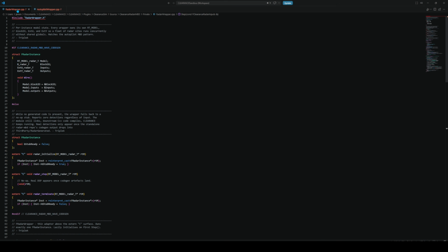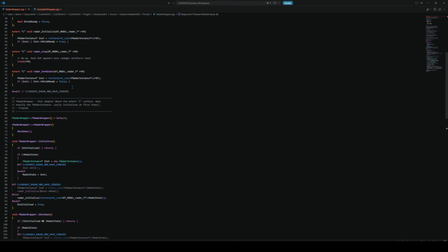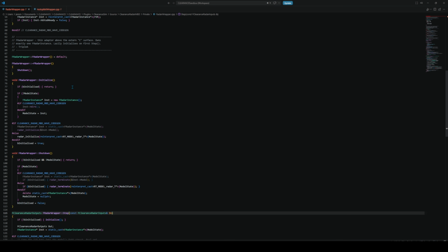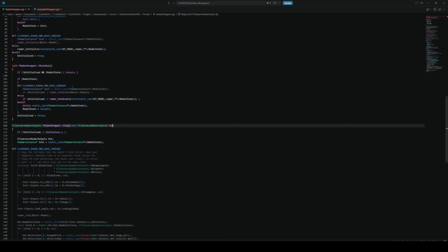And the radar wrapper is sort of the same pattern. You feed it a cube of IQ samples, you call the radar step, and you get the detections back. I build that cube on the clearance side, one contribution per aircraft with its range, bearing, and Doppler baked in. Everything after that is just generated code.